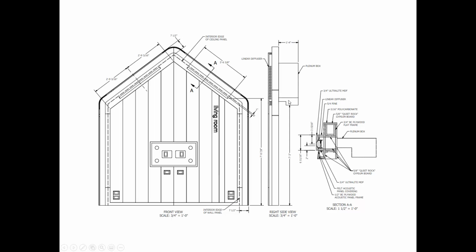But hiding it was also part of the acoustics because we have a fairly good assembly for all this wall. There's a product called QuietRock that was used in here. We tried to get as much mass in there as we could. It did all the things for sound isolation and got a good shell on it. But then we didn't want just 20 gauge sheet metal for the ductwork to be our weak link. So all this was enclosed in something that kind of looked like the wall.